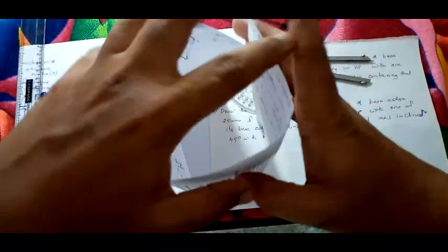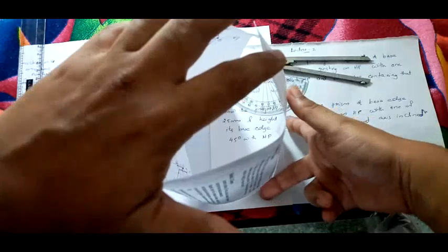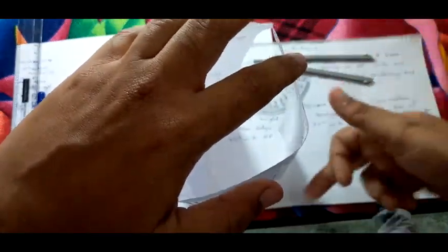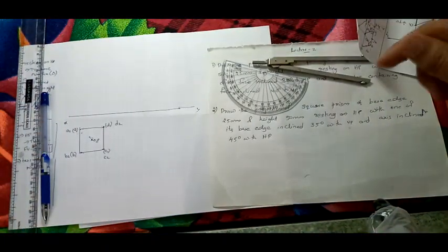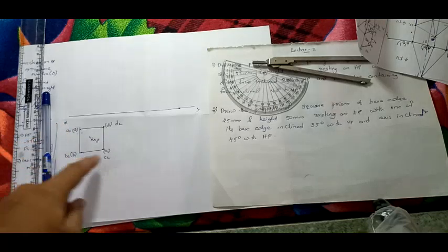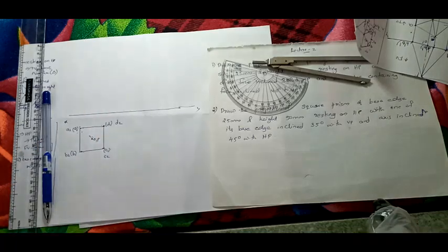If you have a square prism like this, this is your square prism. These will be your face edges 1, 2, 3, 4. There will be a top base and a bottom base. A1, B1, C1, D1 will be your bottom base and A2, B2, C2, D2 your top face. How do you understand the top face? Top means that it is visible. If you are looking from the top, what is visible is A2, B2, C2, D2. That will be your top, and those in brackets are your bottom. Bottom is not visible, right?